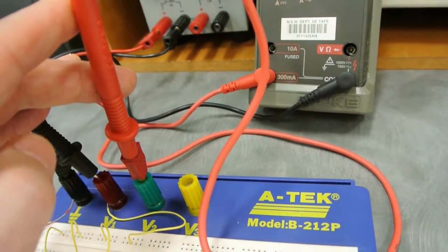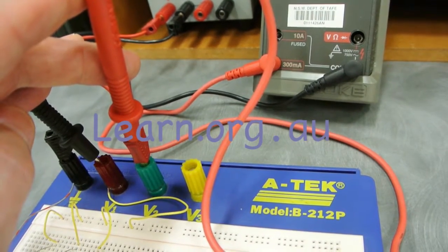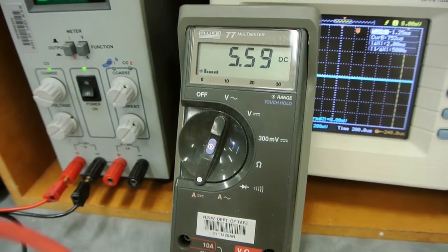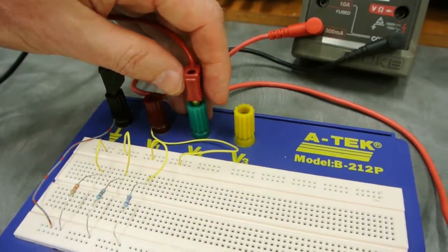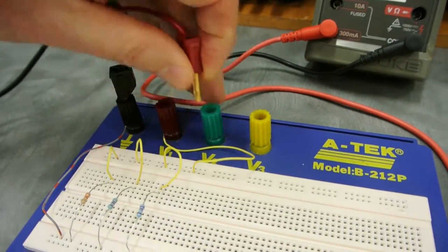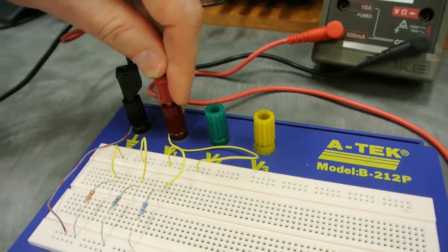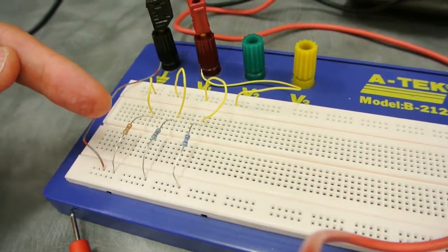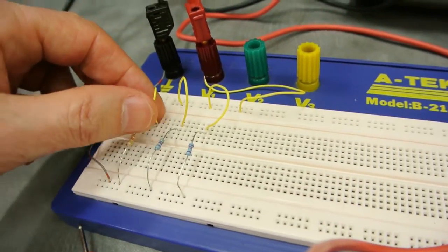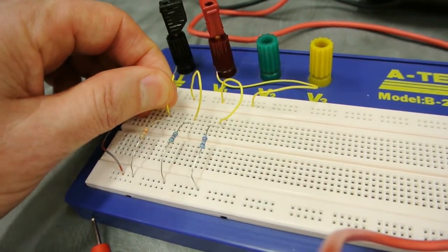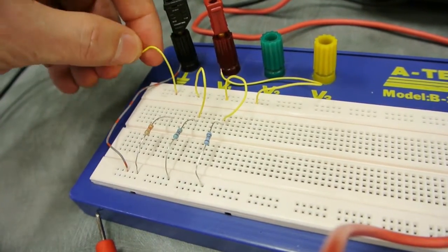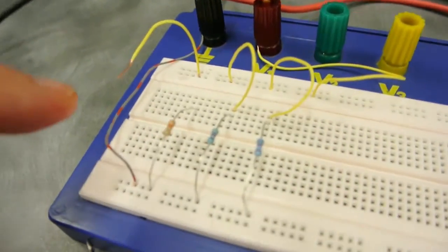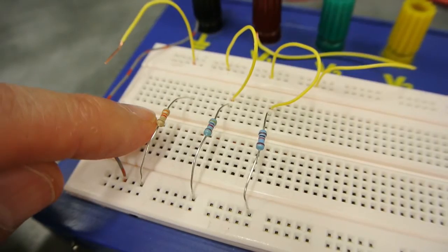And then we already saw I had 5.59 milliamps of current measured into the circuit. Now I'll go ahead and start putting the circuit back the way it was. I've got the 9 volts coming in now, supplying all 3 resistors, but the table calls for us to measure the individual branch currents. So I'll do that by first of all disconnecting the 3.3k ohm resistor, and then we'll have a look at how we measure the current going through it.